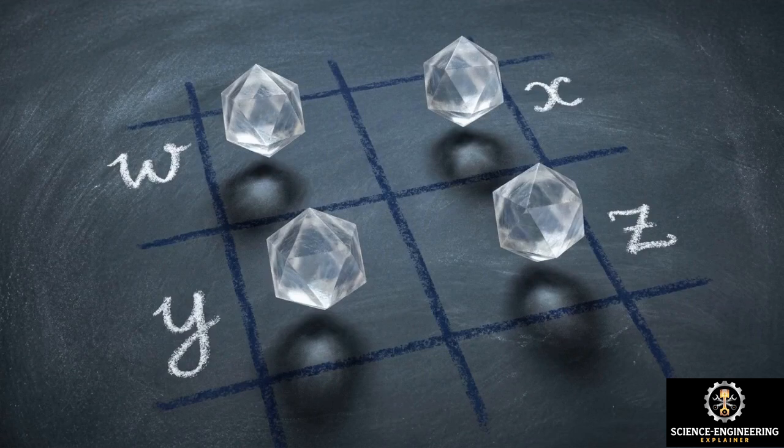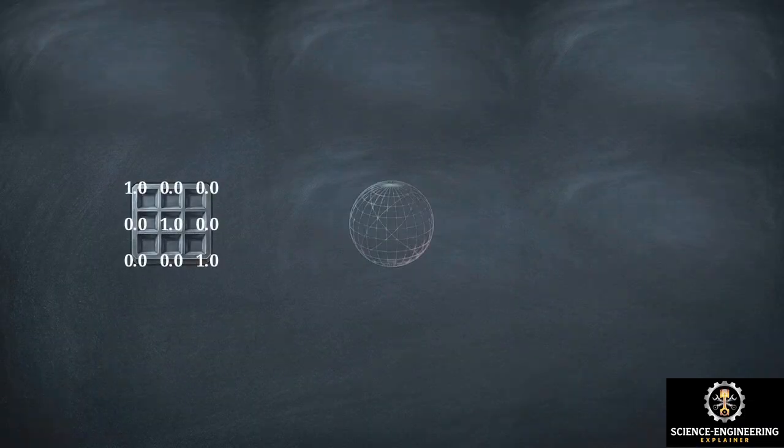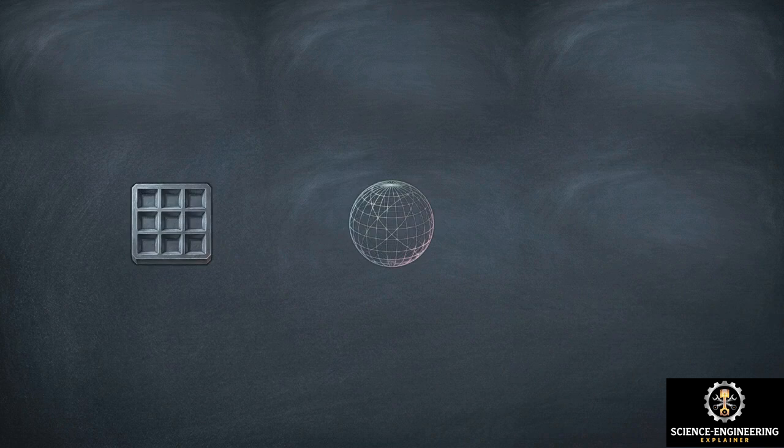The solution adopted across the robotics industry is the Unit Quaternion. This is a mathematical object that safely maps the curved SO3 space onto the surface of a four-dimensional unit sphere, labeled S3. This diagram shows a complex 3D rotation matrix collapsing into a single clean coordinate point on the S3 sphere. The equation governing this is the Quaternion formula.